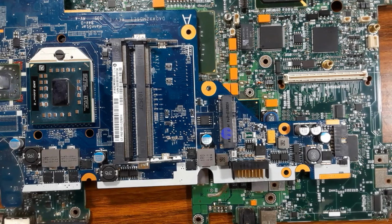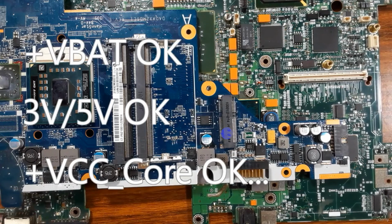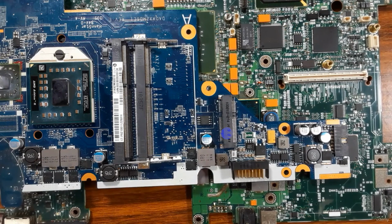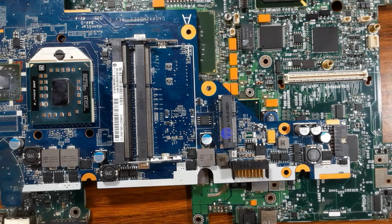The next failure is when you check all voltages in the motherboard, and you find that all voltages are present. You find the 19 volt, you find the 3 volt and 5 volt. Computer is on, all voltages are present. The 5 volt for the USB connector, the 3 volt are present. At pin number 8 of the BIOS, you find all voltages, but the computer still shows nothing on the screen, still a black screen or white screen.